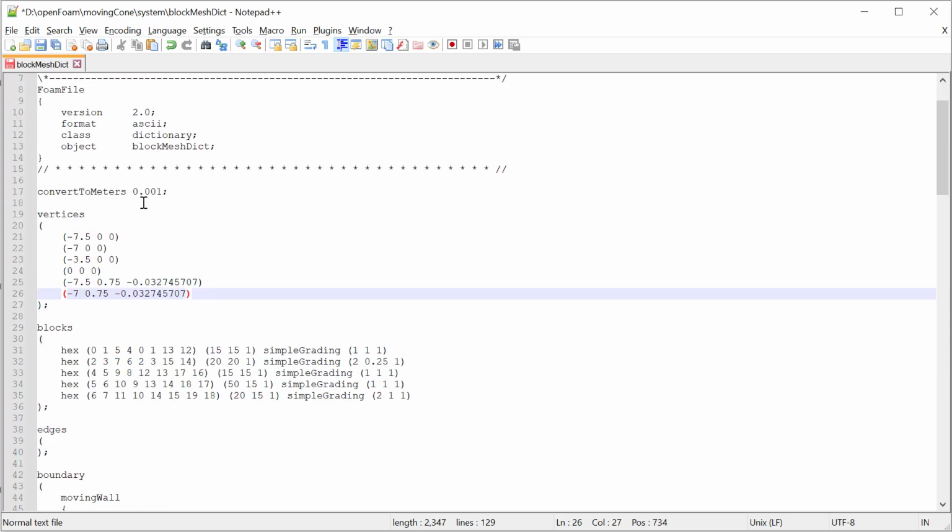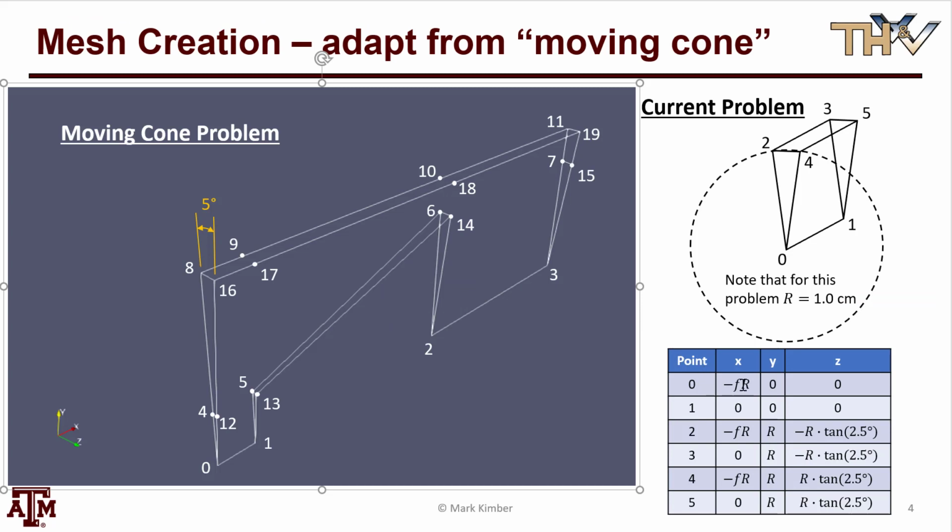And the first one is going to be some factor f, and it really doesn't matter what I choose because I'm only going to have one mesh element in that direction and one mesh element in the wedge direction, in the z direction. And it's in the radial direction I want to discretize, so I'll have 50 or so elements there. And so at the end of this tutorial, I want to be able to do some parametric studies. I want to say, well, what if R was something else? And I want to be able just to change that and run it without having to recalculate everything.